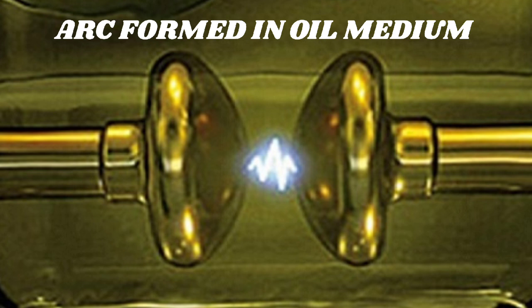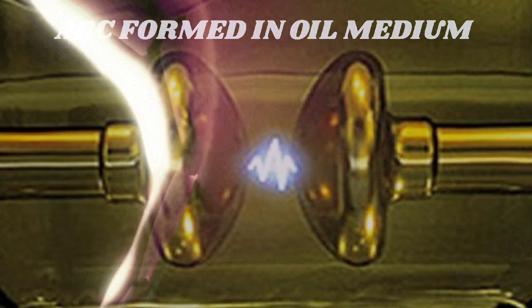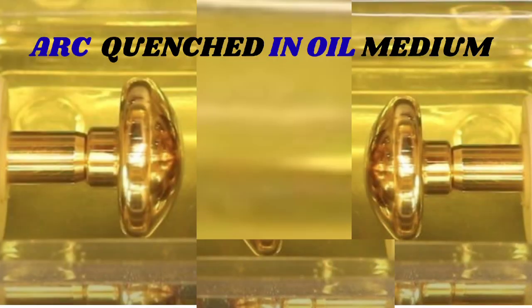When a circuit breaker interrupts a circuit, the arc quenching process unfolds in several stages. As the contacts separate, an arc forms between them. As the contacts move further apart, the arc stretches and elongates. The oil surrounding the contacts then insulates and cools the arc, reducing its temperature and energy. At the same time, the arc is extinguished, and the circuit is safely interrupted. So, this is how oil circuit breakers operate to protect our power system.